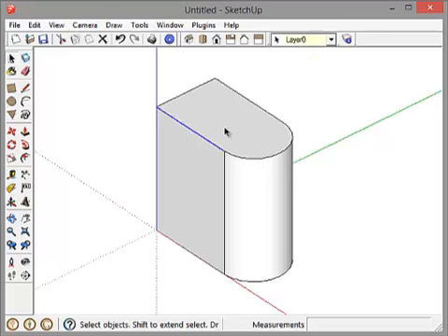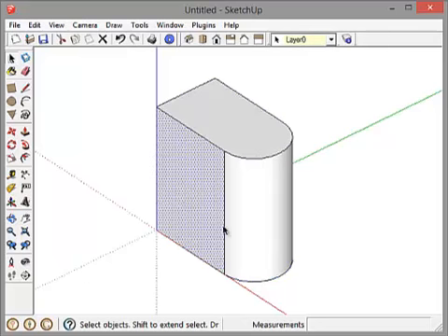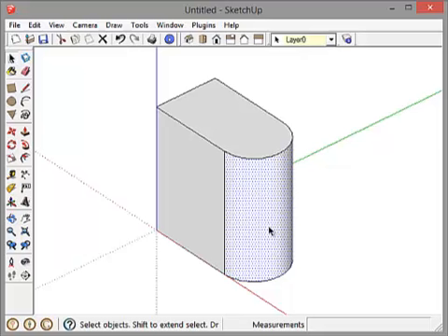And choose the Select tool, and I'm going to look at the components here. I notice that I've got lines like this. I've got an arc here and here. And I've got faces. These are called primitives. When a component is in its primitive state, it is subject to being attacked. And how can it be attacked? It can be attacked by a line touching it that is not intended to touch it or is not intended to be part of it.